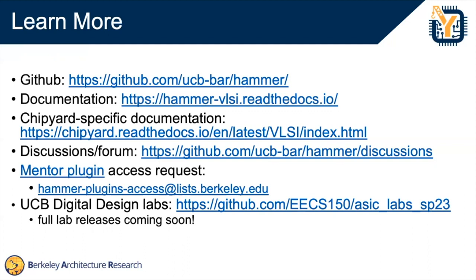Yes. Can you comment on the ASAP7 situation? Yeah, so I think Skywater has been tested thoroughly with OpenROAD, ASAP7 a lot less so. If you have any specific things that you're dealing with as you're working through them, please reach out to us. I think we have at least some small designs working, but being able to get very large designs to go through completely DRC and LVS clean is not that easy.